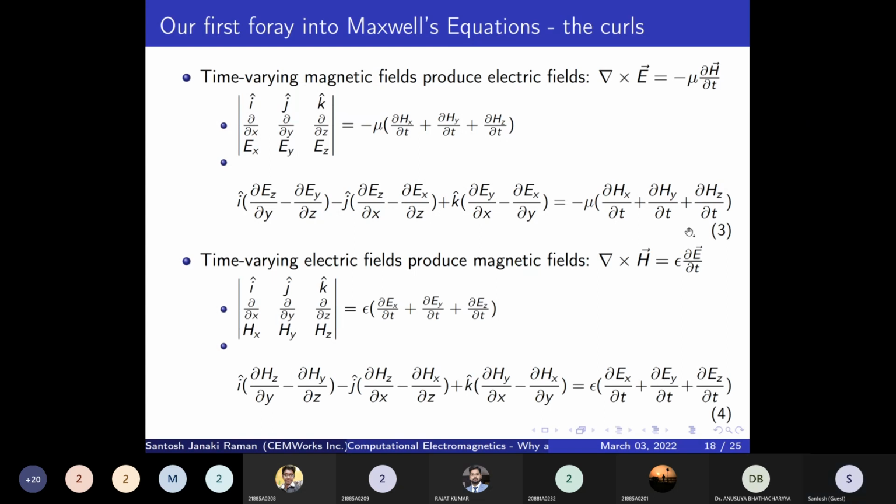Now, let's say you're modeling an antenna or a radar system, then you will have to consider all these crazy differentials when you form the difference equation. That is, you have to discretize each one of them, separate the variables, and march individually in the x direction, y direction, z direction, and then t. You have to march in all four of them. If you want to model an antenna, you'll have to take all of them, right? And you probably won't even use them in this form. You will use cylindrical coordinates depending on what kind of antenna you're using. So it can become complicated in a different way.